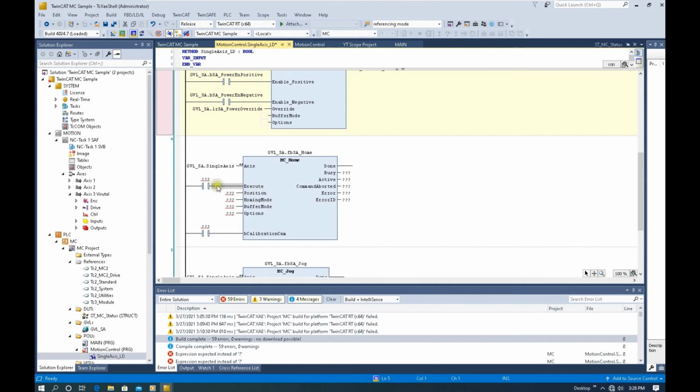So usually we will use this execute and set the position value directly to the axis. We will set that homing mode to a direct mode, which basically means the passive mode. We trigger and set the value. But for some packaging machines, especially those that use an incremental encoder, we will probably use the active home, allowing the axis to go and search for the home itself.